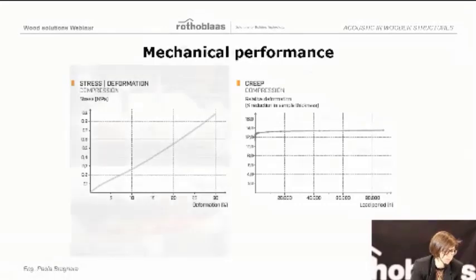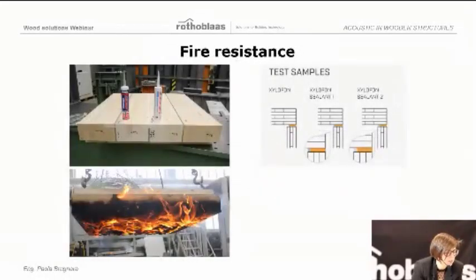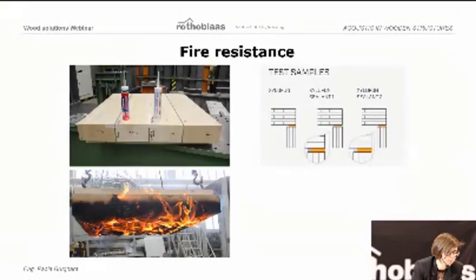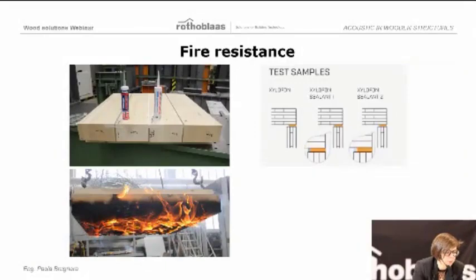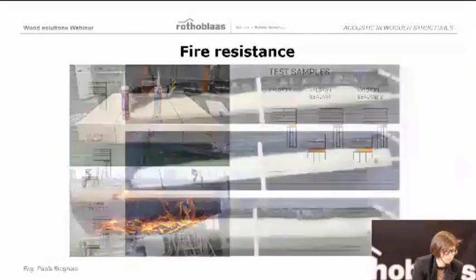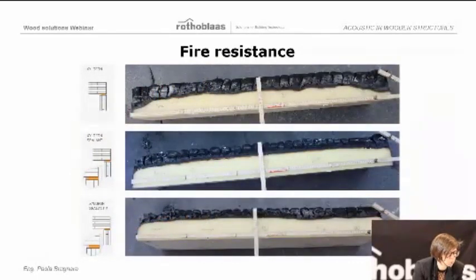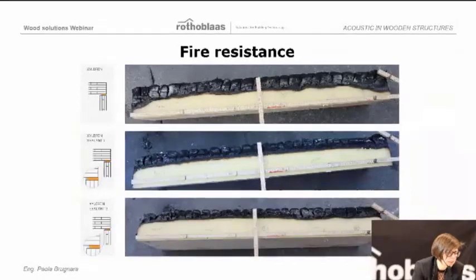from a static point of view we will not have problems. The profile will be installed inside a timber building, so the fire behavior of the product is also important. We have tested the Xylophone installed, exposed to a flame and protected by 2 different types of sealant. And here are the results. As you can see, there is no big difference between using or not using the sealant. And what we can see is that the profile, let's say, burns at the same speed as wood. So having the profile or not having the profile, it is the same.